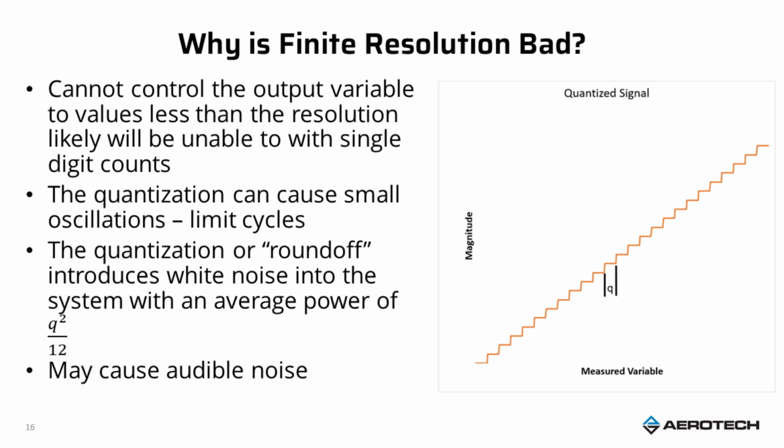If you're working with applications that are really noise sensitive and you're trying to, say, measure the shake, rattle, and roll of a device, then higher resolution also may be beneficial to eliminate noise from the system. And then finally, while resolution can affect accuracy, you have to make sure that you have enough resolution to meet the accuracy that you're trying to have. And a usual rule of thumb is, well, you better have at least 10 times the resolution as the accuracy that you're trying to achieve.